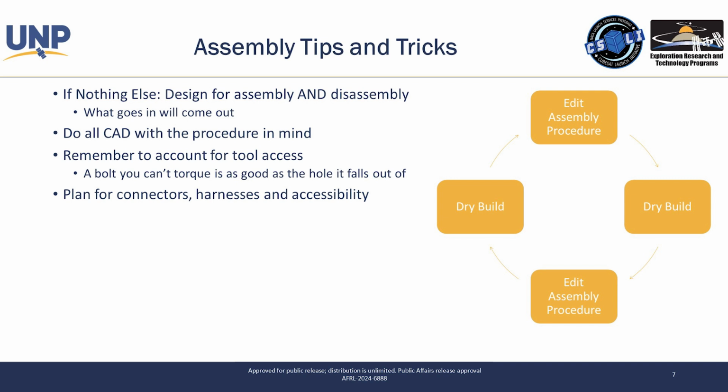Maybe it doesn't fit. Something that's really easy to forget in CAD, because you just make the mate and it's all good and you plan your route, but you didn't actually plan for it to be able to plug or unplug. And that access is very, very key. So keep that in mind at all times.